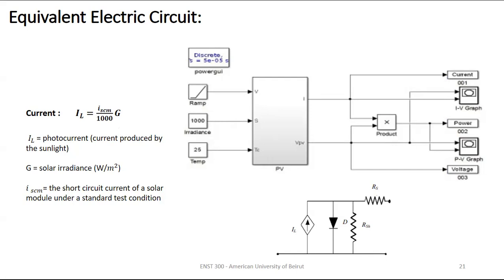The solar panel's equivalent electric circuit model, as shown here, is made up of a series resistor, RS, a shunt resistor, RSH, and a diode. The series resistor represents the series resistive losses actually present in the solar panels, which are caused by the movement of current between the parts and also by the contact resistance. The shunt resistive losses occur because of manufacturing defects, and they tend to increase when the sunlight is minimum. The diode is used to protect the electric components from the current fluctuations.